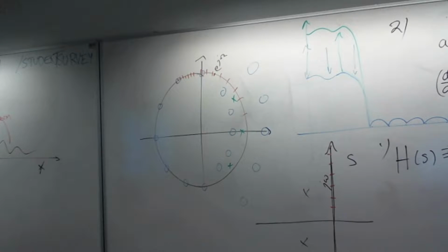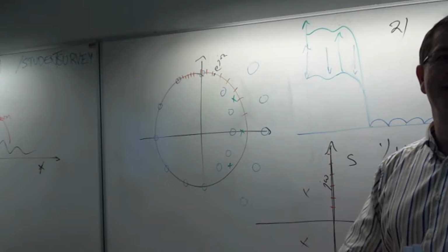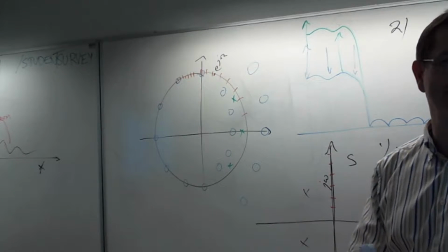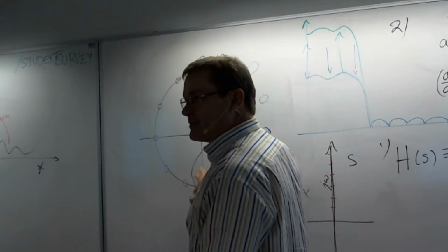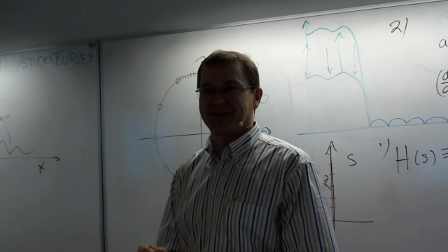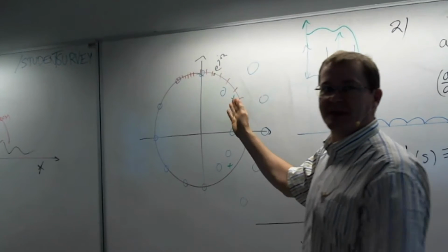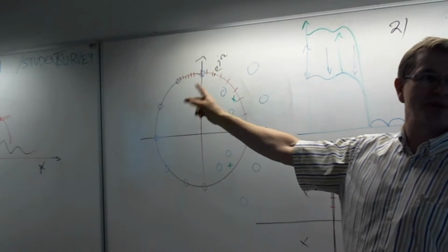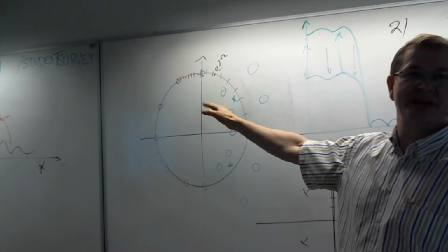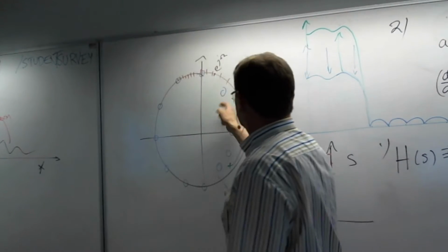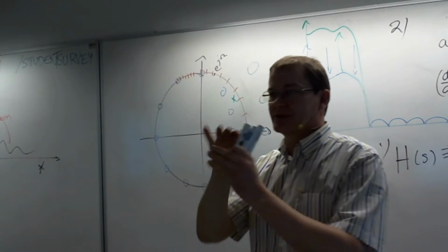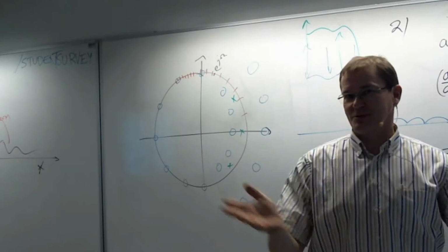And then the third one, direct design. It takes some balls to do it. Direct design means that you just start putting the zeros and poles in the positions you think they would be in the first place. Then you start twiddling these parameters a little bit to match exactly what your filter design is supposed to be.